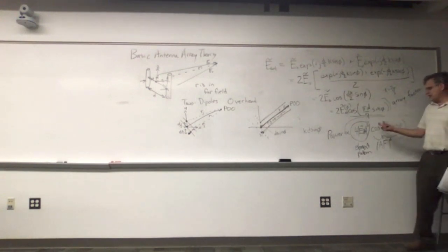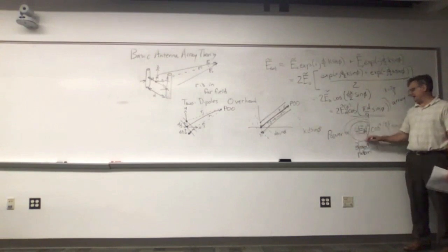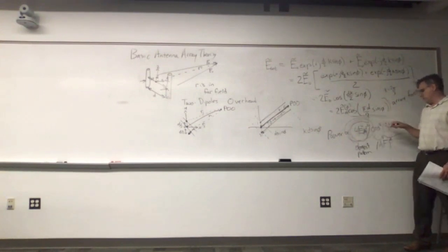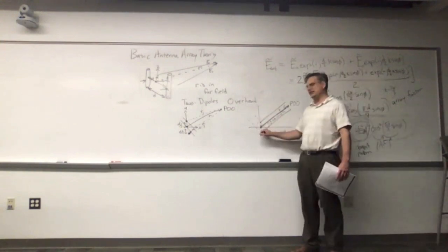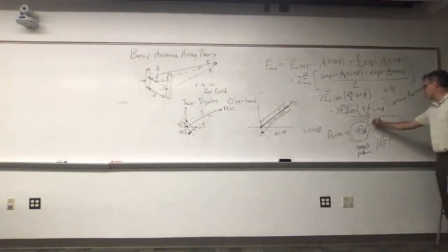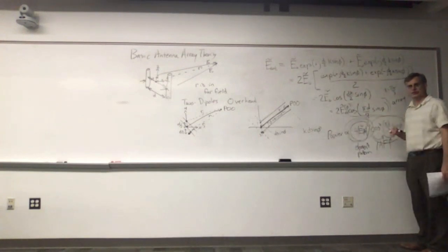Or, I can drop in patch antennas or Yagi antennas. I can make an array of Yagi antennas. Those will add some directionality here. But if it's in the same place as my 2 elements, if I put 2 Yagis here, it will have the exact same array factor, and the total pattern is the multiplication of them.